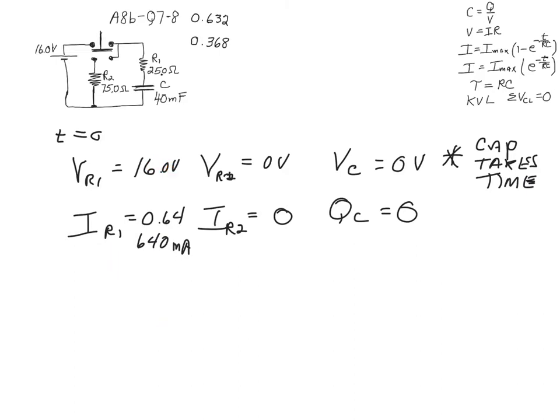So that's going to follow the decaying equation, according to the time constant. So the time constant, of course, will be, let's calculate it. Okay, the time constant ends up being 1,000 milliseconds, 25 times 40, or 1 second. That was purely accidental. So that means after 1 second it's going to be 63% charged.